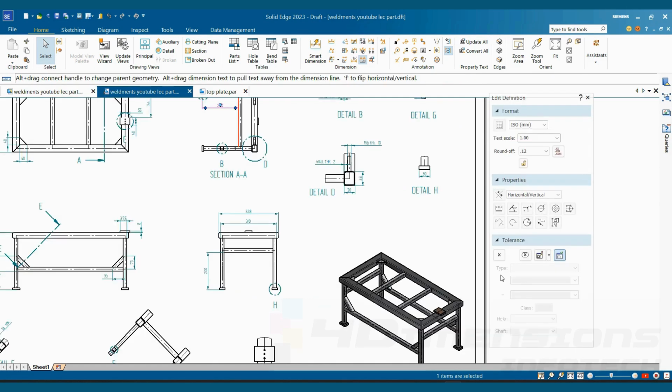Now the definition of the tolerance, we can spell it as deviation from the exact value without affecting the working of the particular feature or object. Means tolerances are applied to compensate the differences which are occurring by the exact value so as to make the part work correctly and also support the interchangeability between two parts.